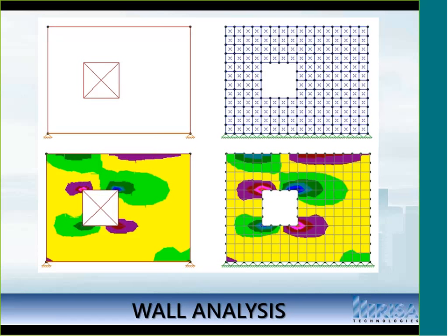Of course, when it comes to masonry, things like outright stress within elements here aren't very useful for us for design. Of course, there is allowable stress design, but that's based more so off of getting a bending stress or an axial stress or a shear stress. And none of those are going to be directly reported by the plate elements.